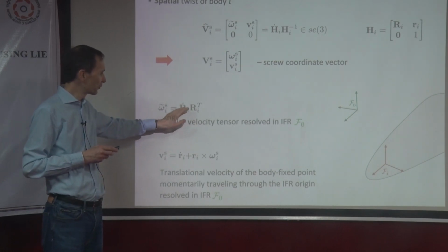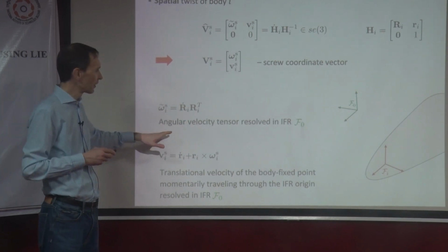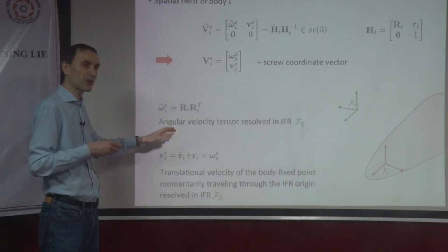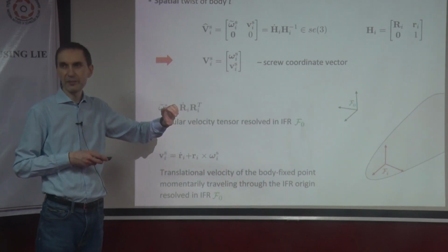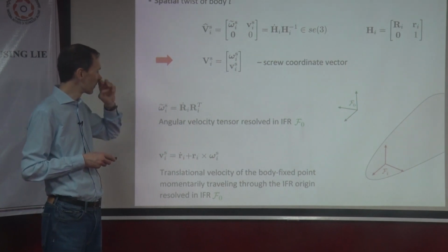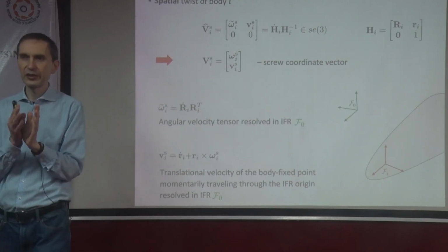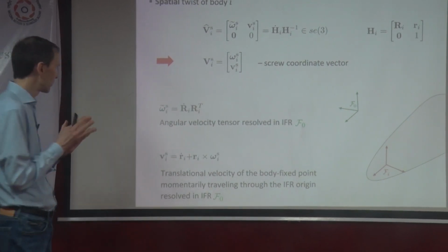Now, the meaning of this. This is again the angular velocity, but it's the angular velocity of the moving frame relative to the space fixed frame, but now expressed in the space fixed frame. And that is also interesting. And as I was saying, when you are always careful with the indices, then you can see this.